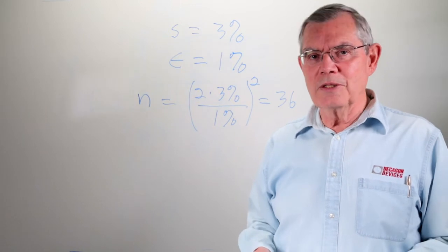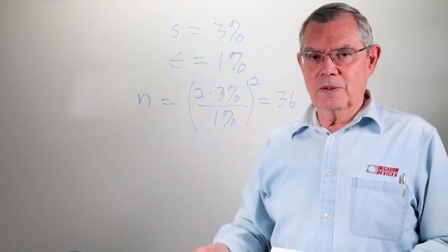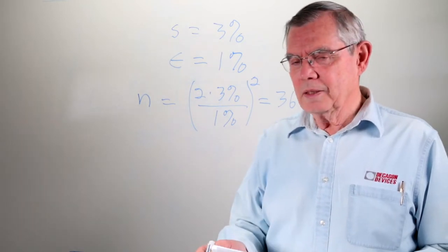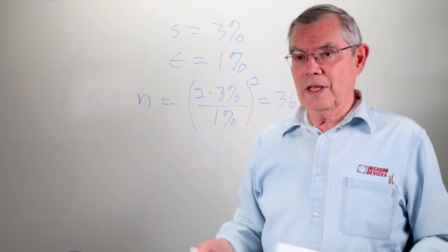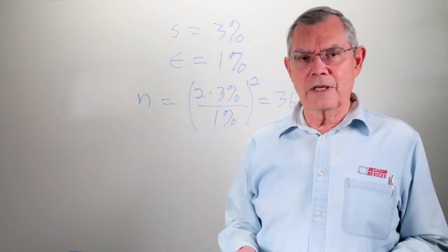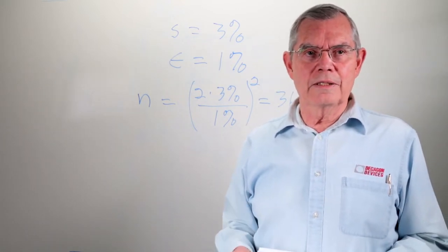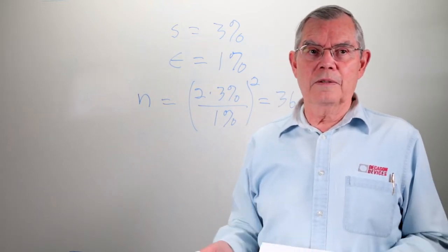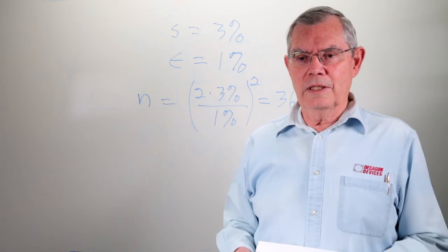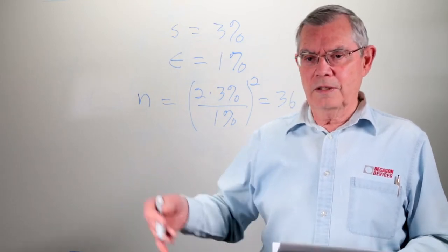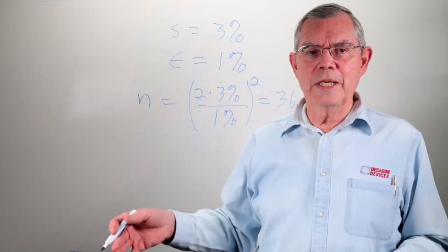Well, when we see that number, typically we get pretty discouraged. That's more samples than we want to take, more samples probably than we can afford to take. To see how that relates to reality, we did a little experiment here. We have a soccer field out behind the Decagon building, and so we went out and took one of our sensors, the GS3, and hooked it up to our little handheld device, and we set up a transect 20 meters long.